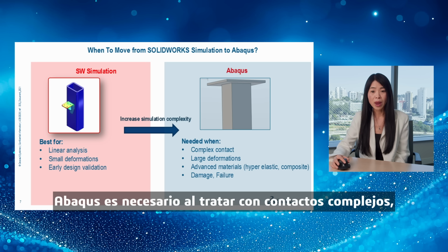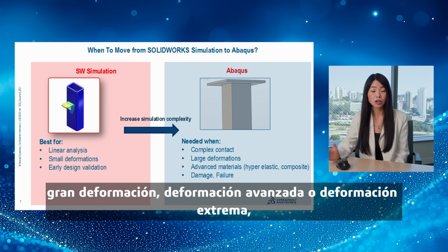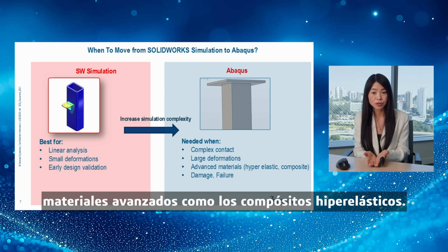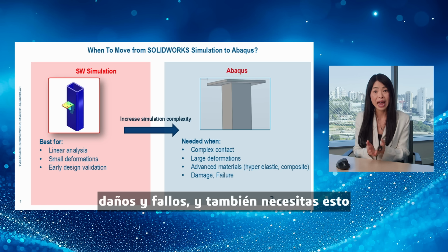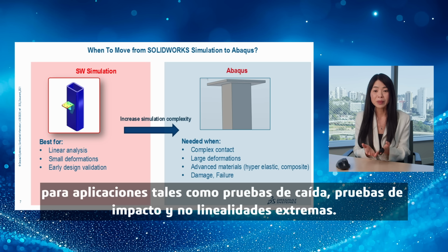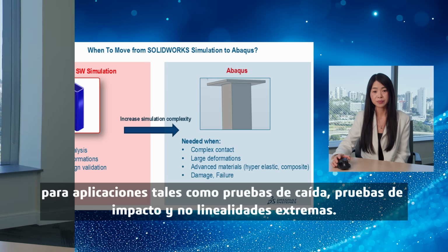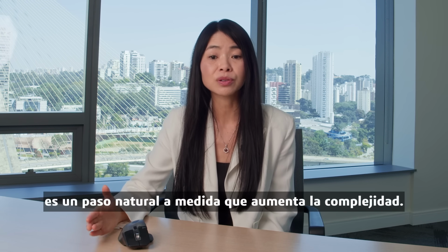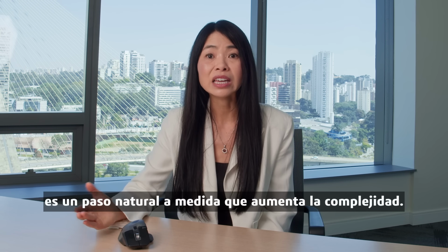Abaqus is needed when you have complex contact, large deformation, advanced large deformation or extreme deformation, advanced materials like hyperelastic, composite. You need it if you need to model damage and failure, and also for applications like drop test, impact, so extreme nonlinearities. So Abaqus is not a replacement, it's a natural next step as complexity increases.